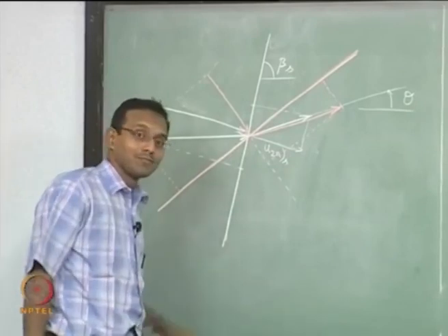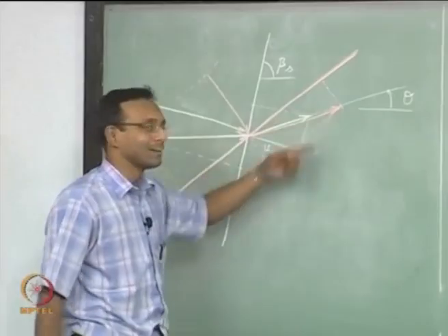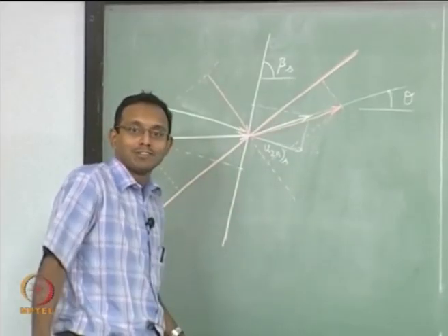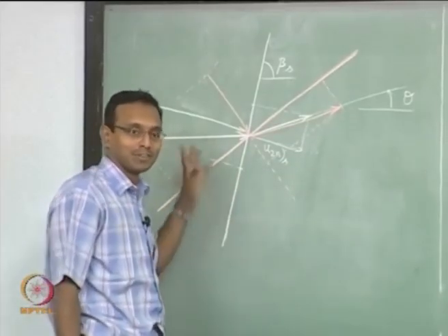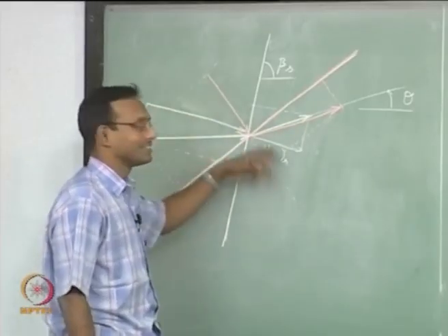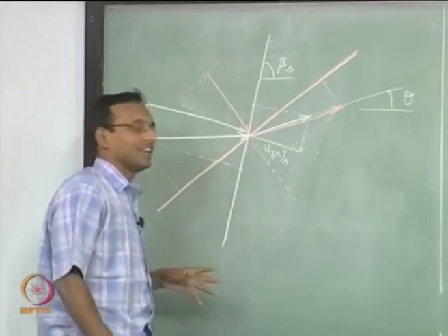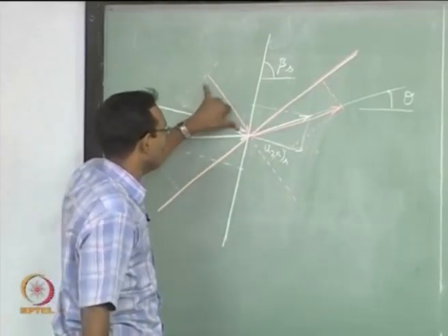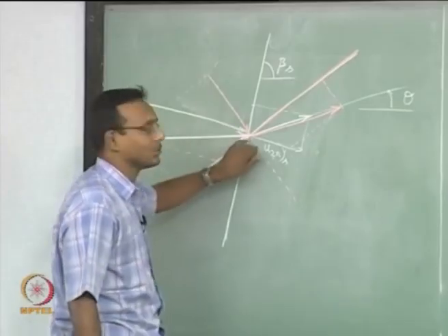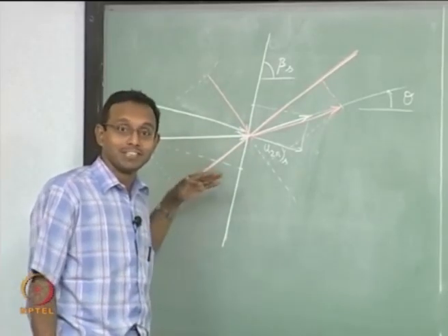Now, you may ask, if I follow the same procedure, I can draw how many ever shock angles I want with the same angle finally. The same process if I follow. If I already fixed the theta and choose beta and draw all this, I can do that. But you should know that I do not have the freedom of choosing u1 normal to u2 normal ratio. That is decided by normal shock relations.